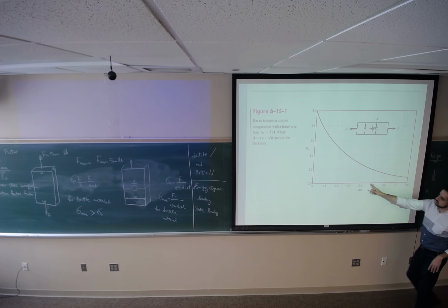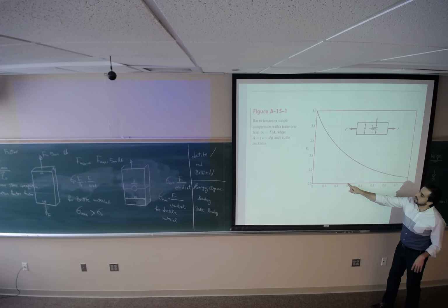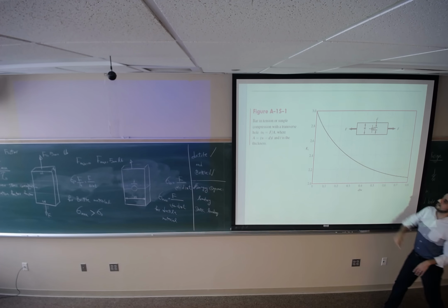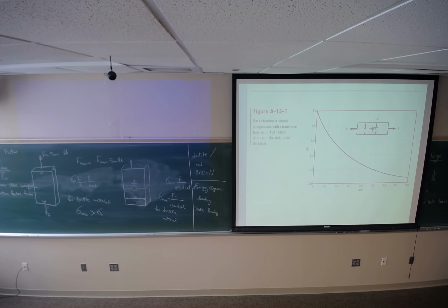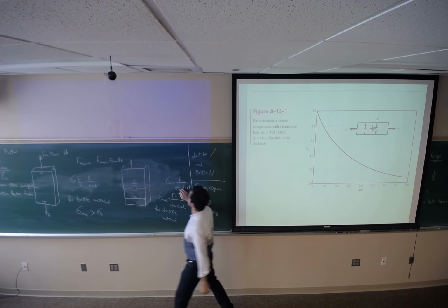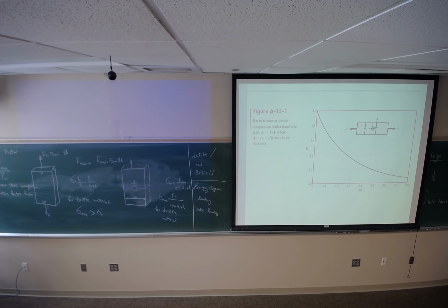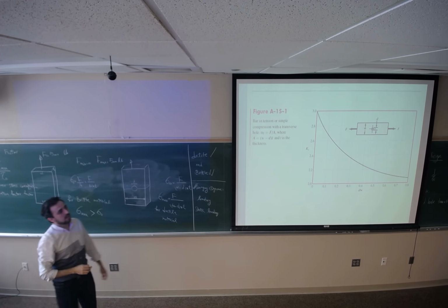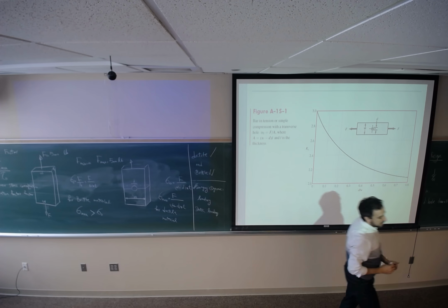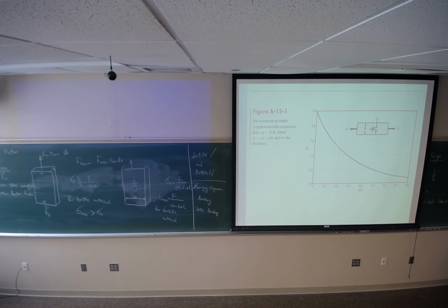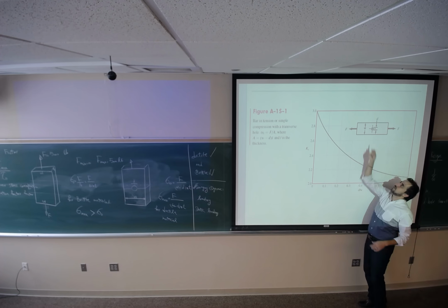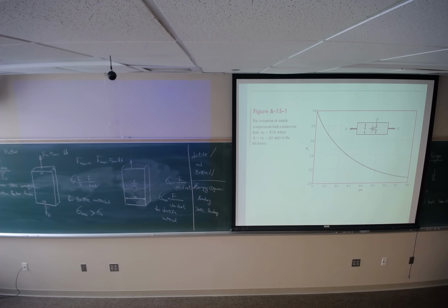So you will find D over W, and then find the corresponding KT. So this is how you can find KT. Then you calculate the nominal stress multiplied by the KT that you read from that graph, and you can find the maximum normal stress applied at this cross section passing through the hole.